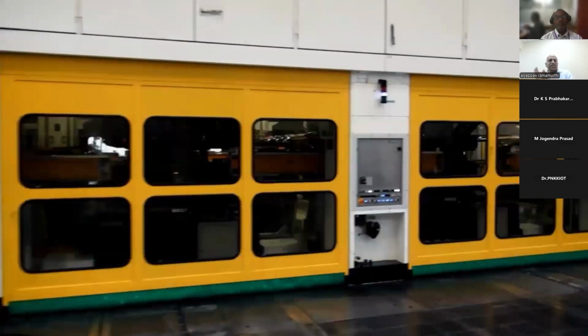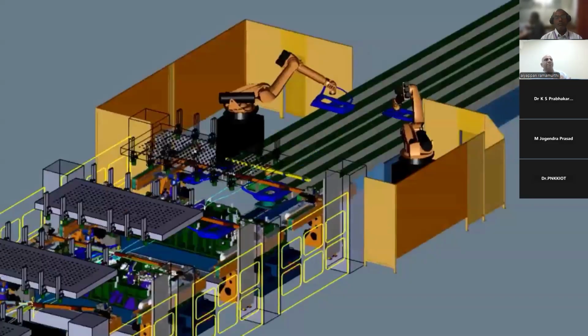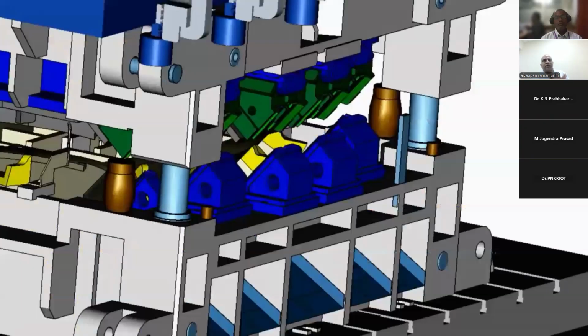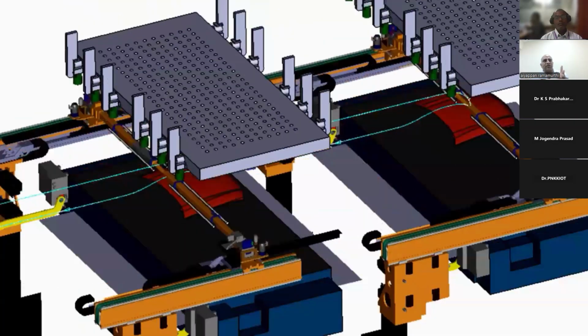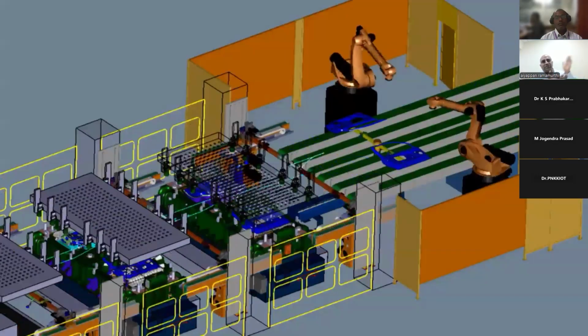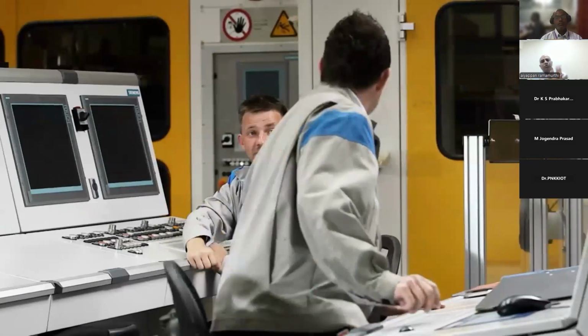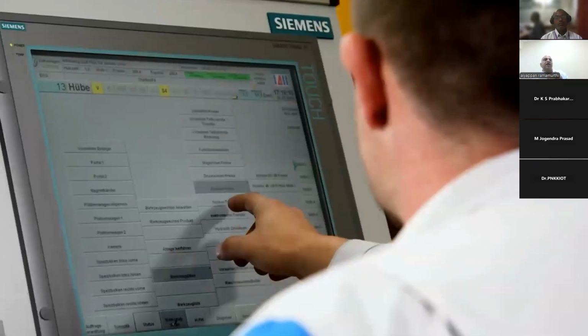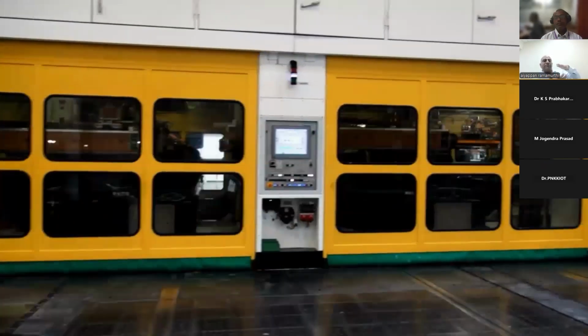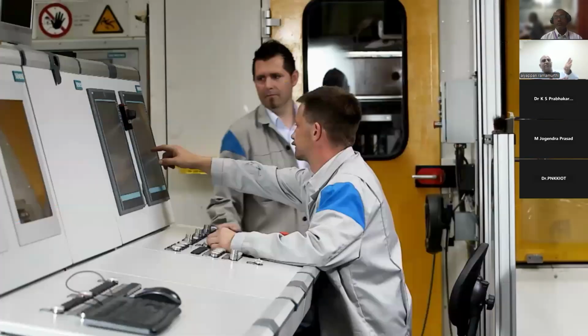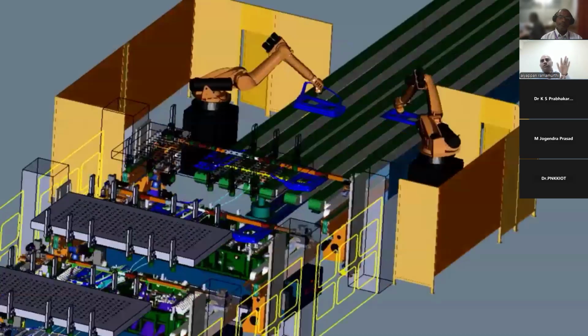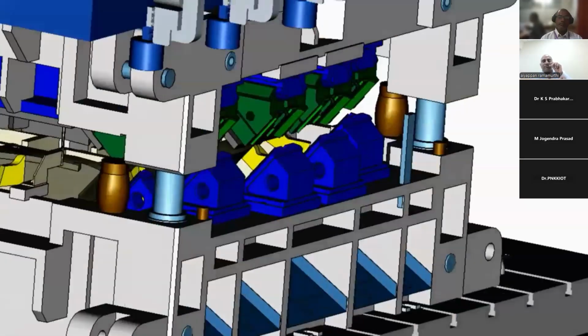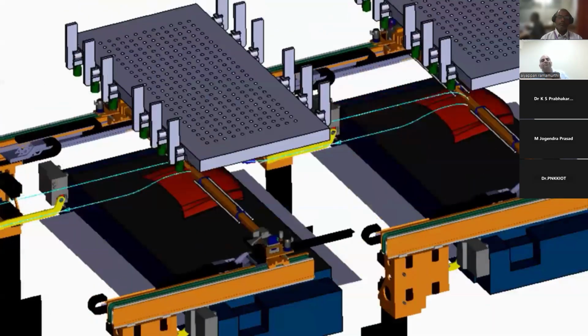We talked about tires also. So there are curing presses. Curing takes 5 minutes, and because of that, tire manufacturers have about 200-300 curing presses. Now, if you are able to reduce the cycle time from 5 minutes by, say, shaving off 10 to 15 seconds, it's huge, because the volume is so high.